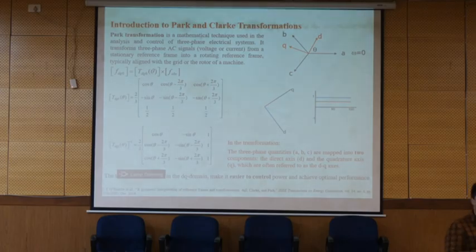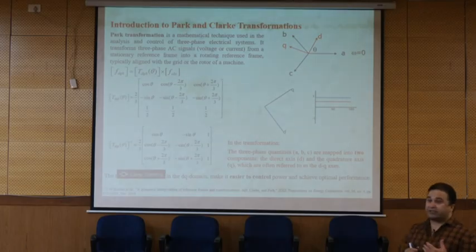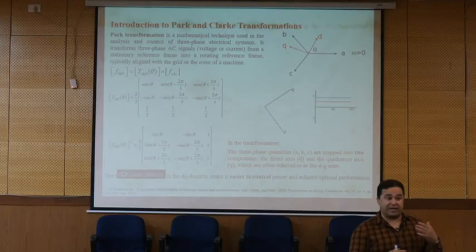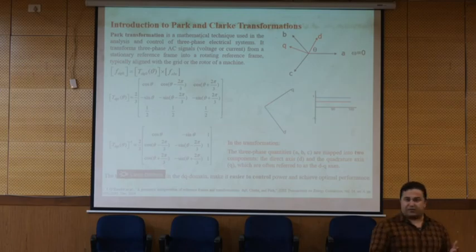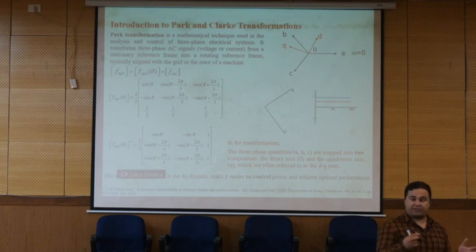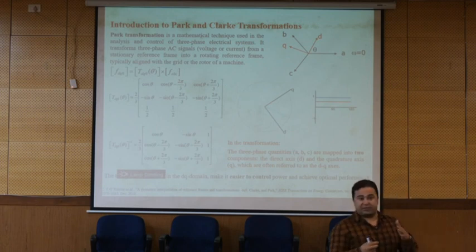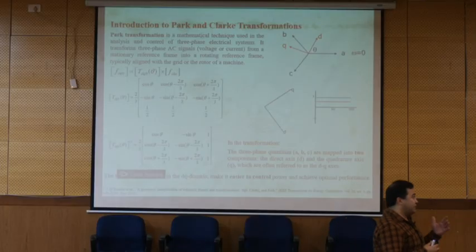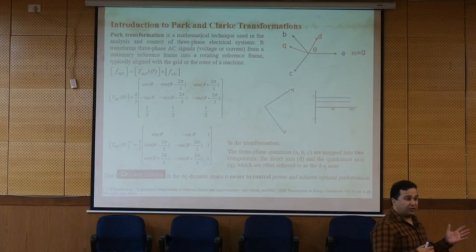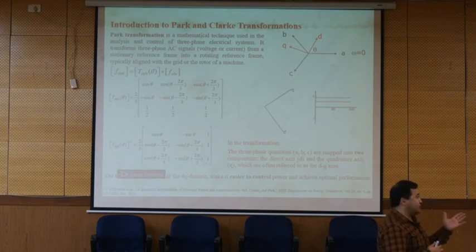In some cases, you have the reactive load, which changes the power factor of the grid, and the distribution company again asks you to compensate it. Otherwise, you should pay the penalty. So for this case, in the conventional technology, they use this capacitor bank to compensate the reactive power on the load side. But the smart solution nowadays is that we use this technique.